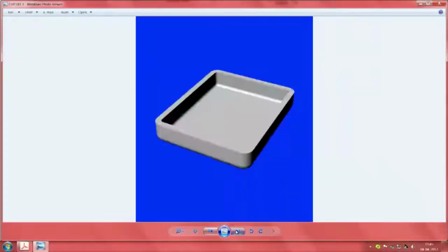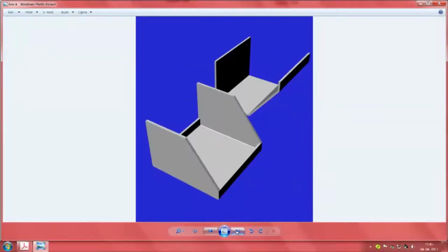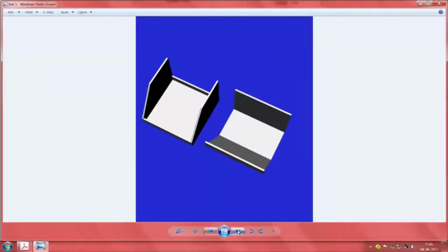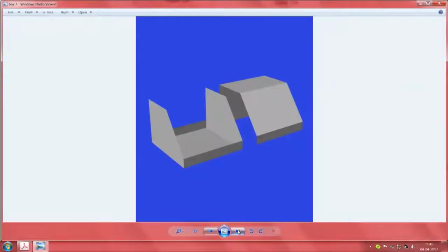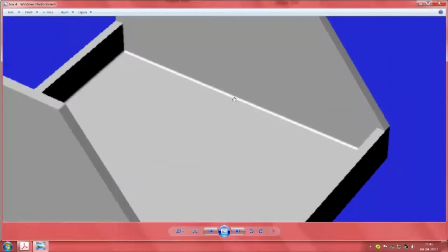Having shown a few of these samples, now permit me to go back to this whole thing. So, in reality this is not easy to produce. You have seen this, no? Well, it looks nice, but it is not that easy to produce. The same box which I showed you here did not have a thickness. This is what has been done in the cardboard model. But then as you come here slowly, we have added the thicknesses here. The moment you add the thickness, we end up with two issues which I thought I will highlight one more time here. One is you have seen here there is a bending radius inside, it is real. Similarly, there is a bending radius here, real.